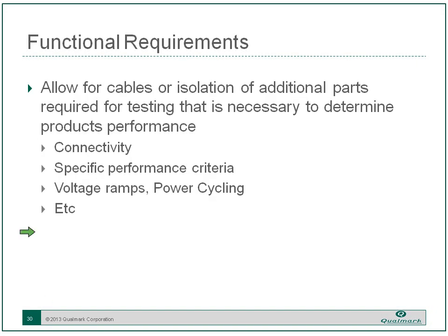When you're thinking about the functional testing, be sure that you've considered all the cabling and any specific performance criteria. One of the things, of course, we run into as we get into HASS is cable lengths will get long enough that you may have issues with signal integrity or voltage drop, and if that becomes an issue, you need to obviously work with some heavier wire perhaps.